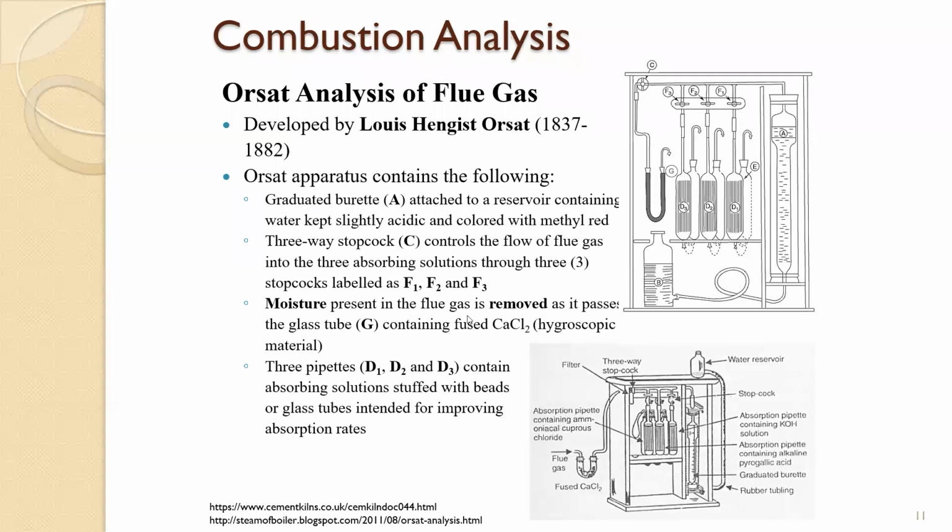So moisture present in the flue gas is removed as it passes the glass tube containing a hygroscopic material. So the calcium chloride absorbs the moisture. That's why the Orsat analysis is an analysis where moisture is removed. It's a dry analysis.